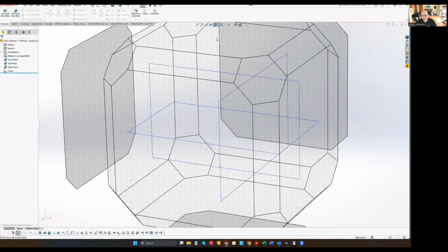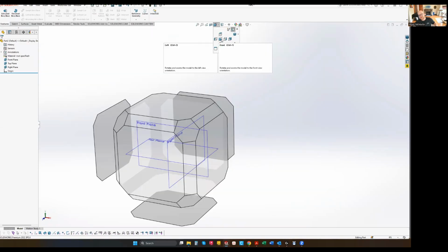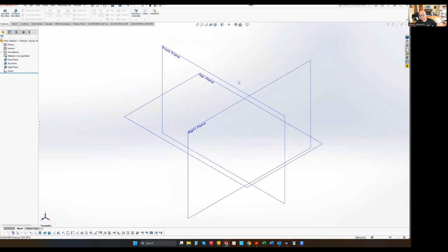So with that also, if you hover over these view orientations, quick views, you can see the top is Control-5, the bottom is Control-6, front is Control-1, and isometric, that won't pop up, but isometric is Control-7, just like that. Remember Lab 5 and the Exam 1, we had a kind of isometric view. It was an offset view, and then you had to draft your 3-view drawing from it. So that's Control-7, and you'll get the hang of that.